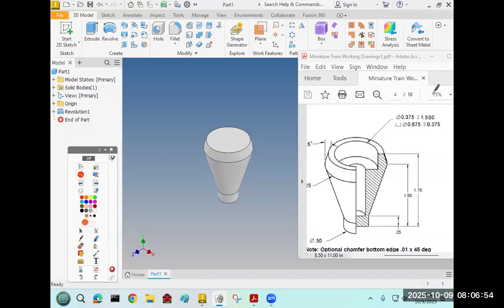It won't let you select it. One of the lines isn't connected. It's probably that green line. Go in and edit the sketch. In the browser bar, right click and choose edit sketch so that you can work on it. Edit sketch 1, I'm guessing. Yeah, there you go. And you could probably delete that green line and redraw it, making sure to snap.